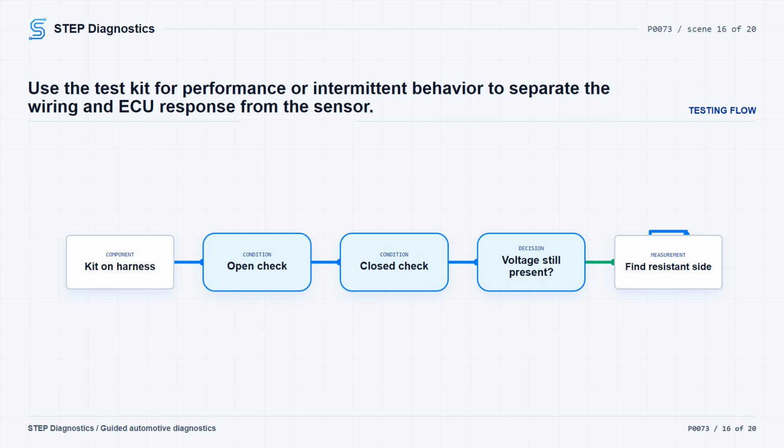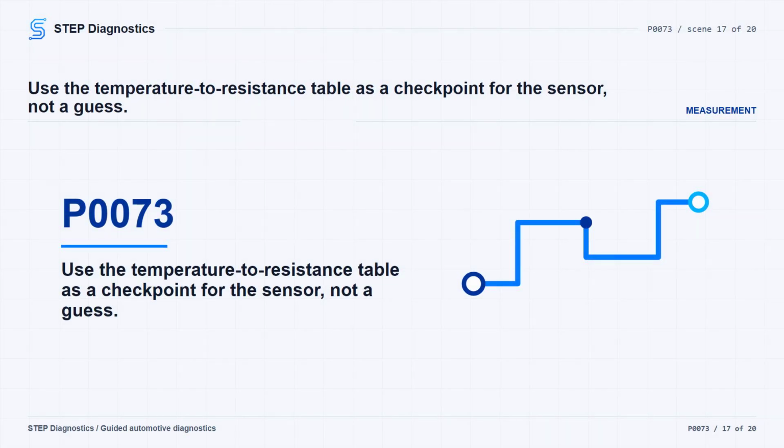If no resistance is measured, carefully recheck the connectors in that circuit path for spread terminals or dirty and corroded terminals. If the circuit response points back to the sensor, confirm it instead of guessing. If a temperature table is available, move the switch to adjust, connect an ohmmeter to the test leads, dial the tool to a resistance value in the table, connect both leads to the temperature sensor harness connector with the ignition on, and monitor scan data for the proper reading.